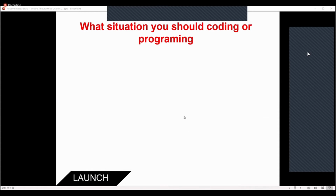Situations where the coding, why we would code. It's just going back over what I mentioned before. So why would we code or program again? Basically, if we change the ECU, and the first coding of the ECU doesn't work, then you would code after programming.